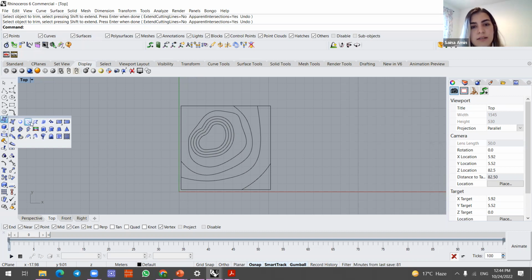But in some cases, like now that we have the whole curves, I think it's not necessary to do this. As we talk about it, there is loft here. When we have two different curves, we can connect them with a number of curves between these two, and it means the loft. We connect them and create a surface containing many curves.